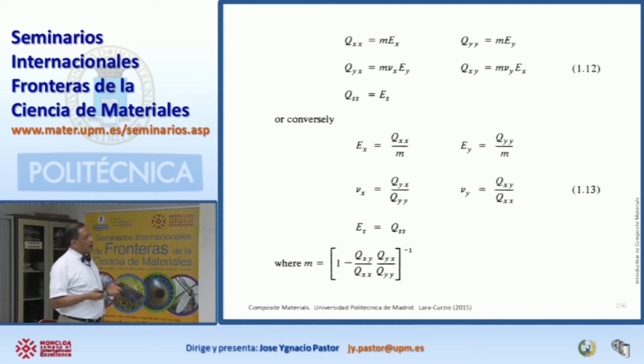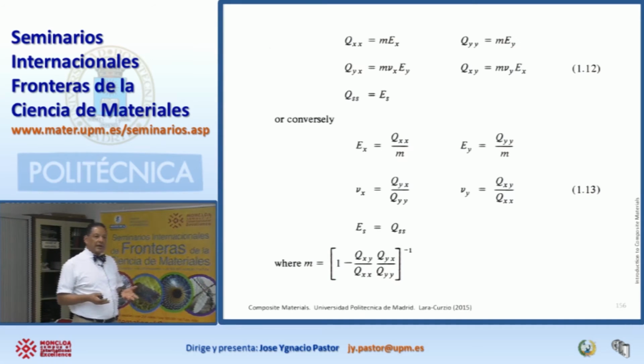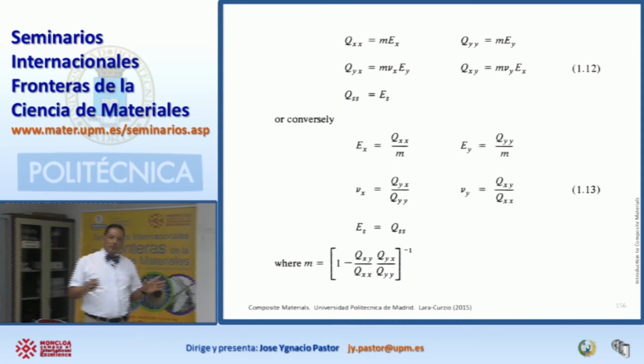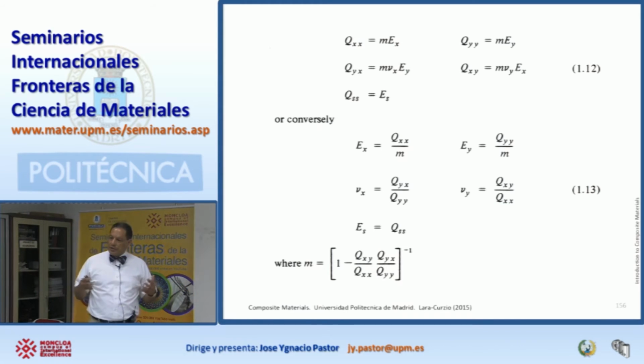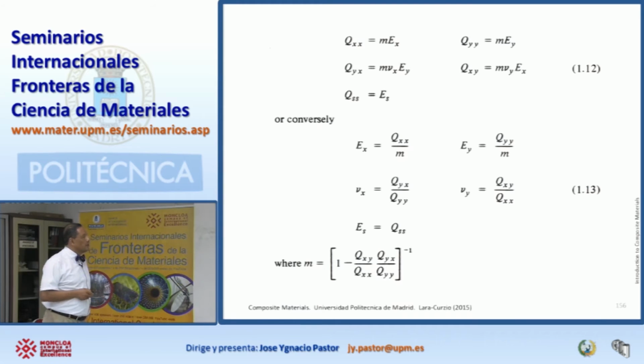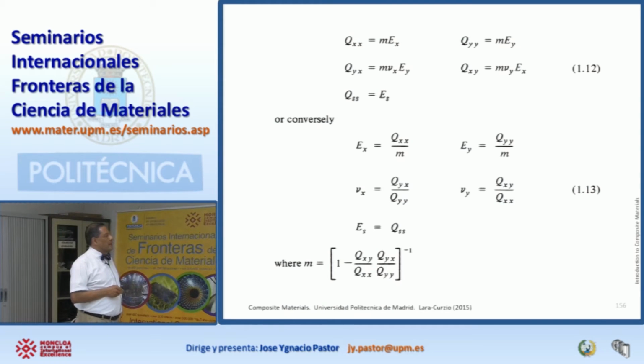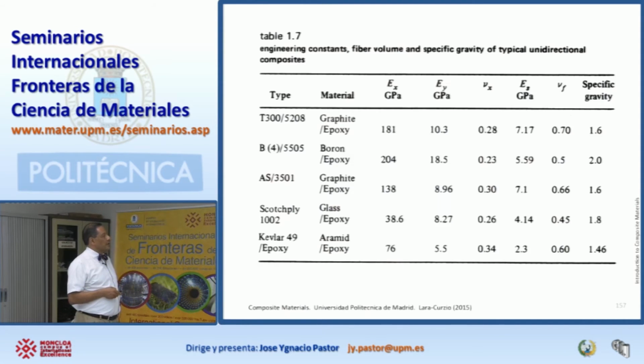And remember that we're only using an elastic analysis, okay? We are not using plasticity. We are assuming that all these airplanes are designed just in the linear regime, where everything is reversible. There is no damage accumulation, and that's really the principle for most design concepts.